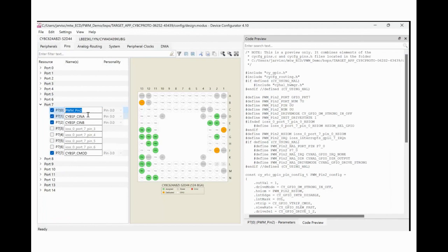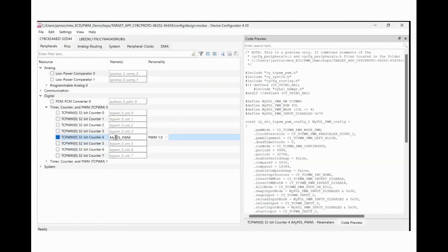So everything you see here in this tool gets wrapped up, along with a lot of other aspects of the hardware itself, into what we call a BSP, or a board support package. And even within my application, I can have multiple BSPs and switch back and forth between them, with each of them having a unique pinout or unique hardware that they're actually running on. And so we'll show that as well. So you see an instance here where I'm using my PWM. That's where those get defined.